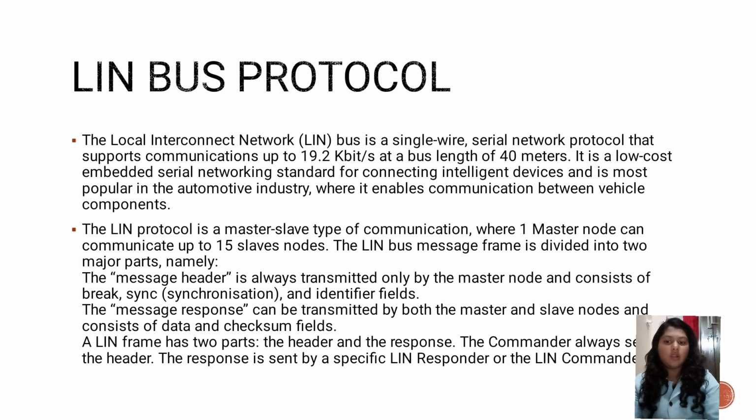LIN bus protocol. It stands for Local Interconnect Network. LIN bus is a single wire serial network protocol that supports communication up to 19.2 kbps at a bus length of 40 meters. It is a low cost embedded serial network for connecting intelligent devices and is the most popular in the automotive industry. The LIN protocol is a master slave type of communication where one master node can communicate with up to 15 slave nodes.